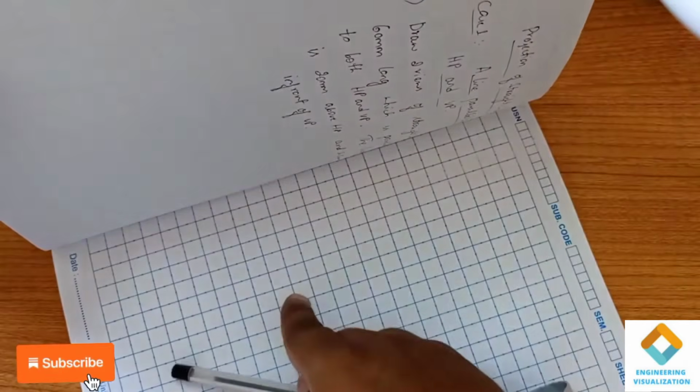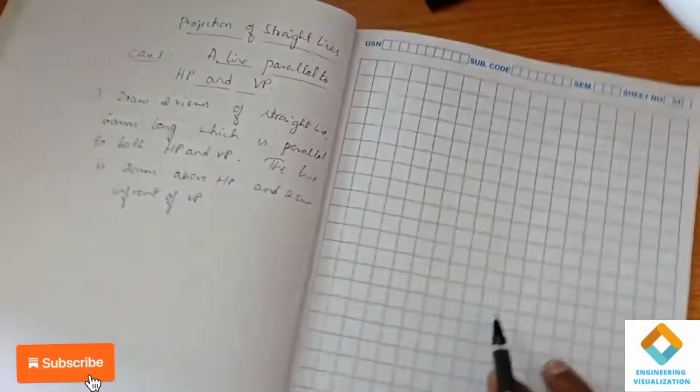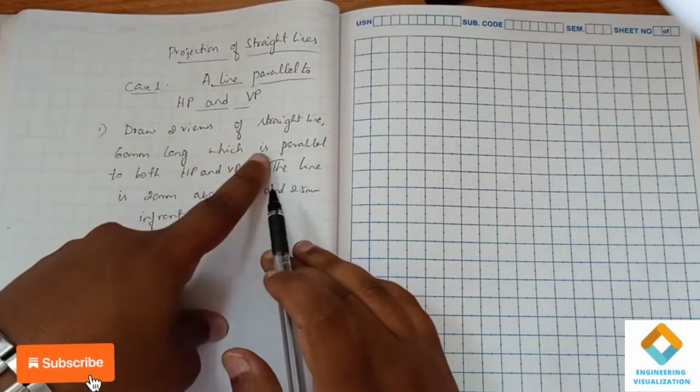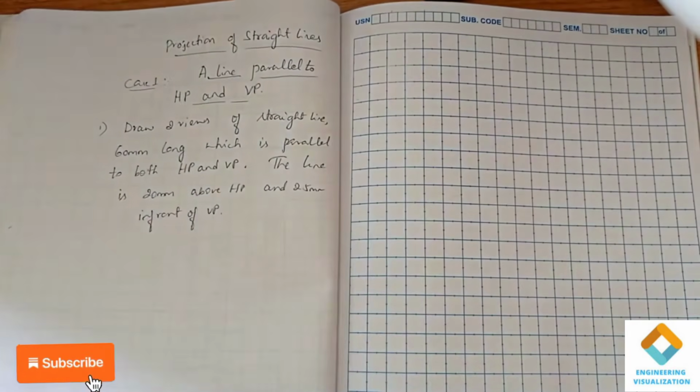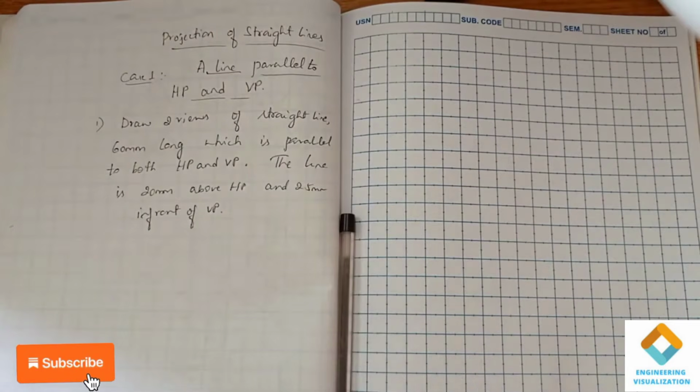This is the vertical plane and this is the HP plane. The line is parallel to HP and it is parallel to VP. So this is our condition, and we will deal with the problem. Draw two views of a straight line 60 mm long which is parallel to both HP and VP. Here you can see that the line is parallel to both the HP plane and the VP plane. The length of the line is 60 mm.